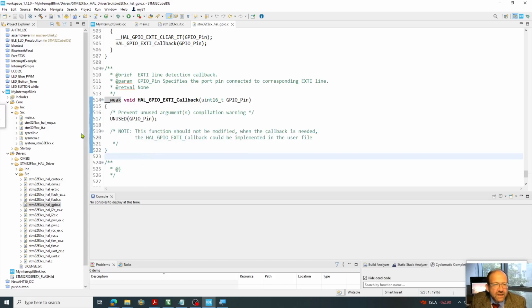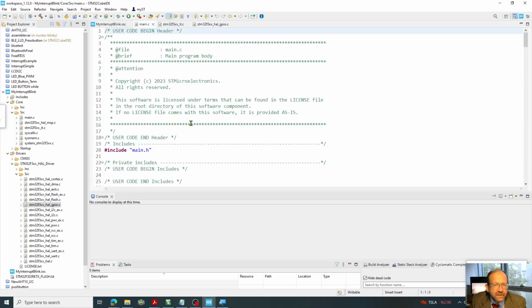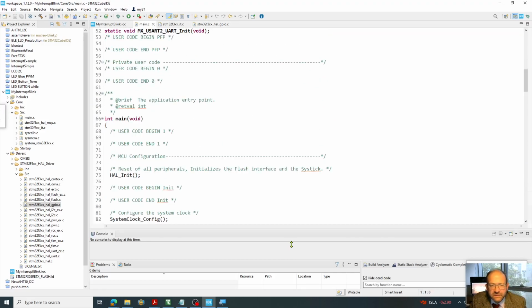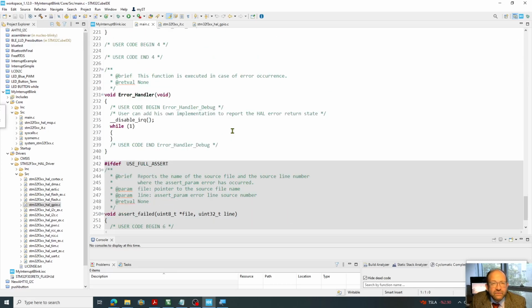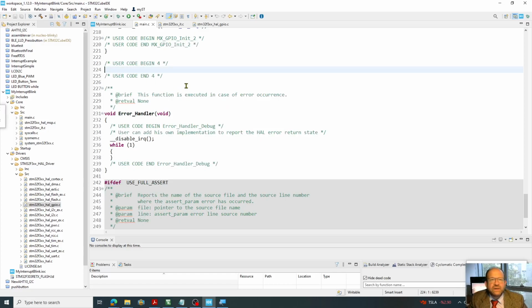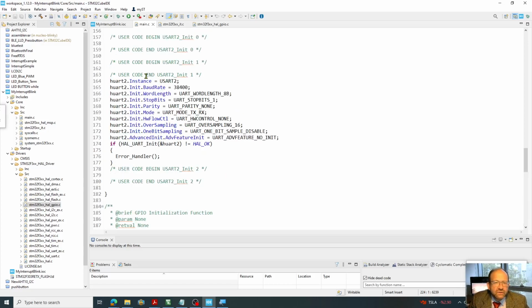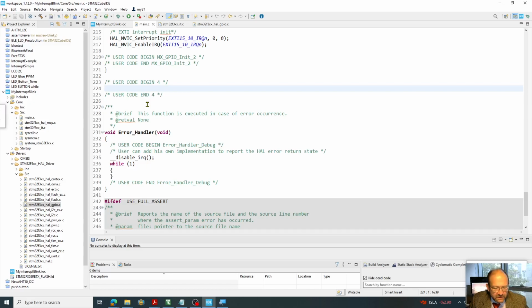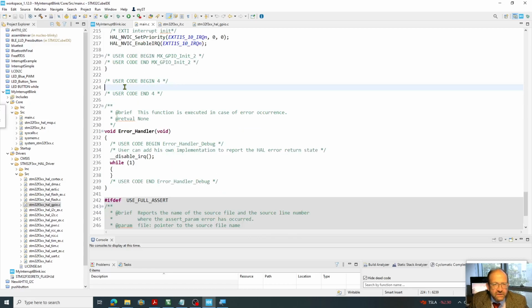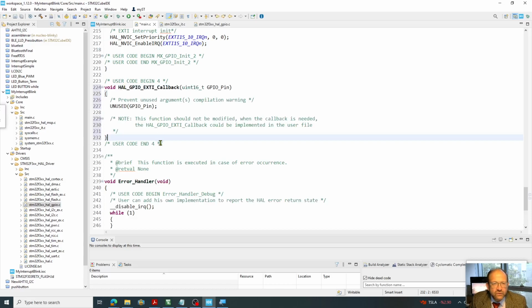And what you do is you come back to your own main program, you come down here into a part where you can actually squeeze in that information underneath. That might be a good place to write, for instance, USER CODE BEGIN 4 is one place to put that. So let me go into that part and then Control V, my code. So what I'm going to be writing here is what I want to do when I press the button. That might be a bit flip on the LED.